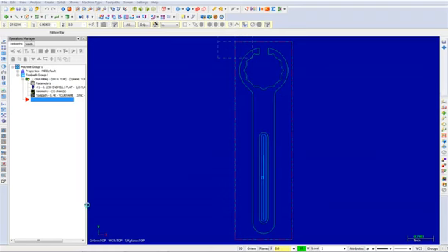In this video, I will show you how to rough the outside using high-speed dynamic core mill. Dynamic core mill machines open pocket shapes or standing core shapes using the outmost chain as the stock boundary. The tool moves freely outside of this area. The inner chain defines the limit of the tool path. They are designed to utilize the entire flute length of their cutting tools to maximize material removal while minimizing tool wear.